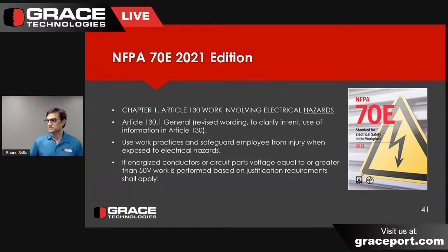So after the permit, we get into the shock risk assessment and the arc flash risk assessment. Technically harmonized, process harmonized between Z462 and 70E, and for arc flash risk assessment, table 130.5C and table 2, I think they're the same. Yeah, they are. And there was one work task that was added related to first energization of a circuit breaker or re-energizing a circuit breaker after significant maintenance, and that the likely occurrence of an abnormal arcing fault is yes.